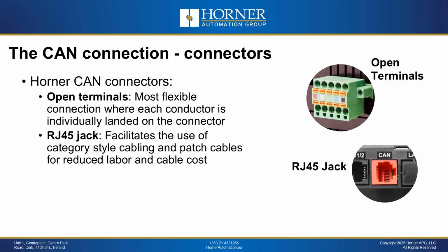Now let's start talking about how you can make that connection with CAN on Horner controllers. We're going to start with the connectors. Horner controllers have two different style connectors that they use for interfacing with CAN, depending on the controller. Let's start with open terminals. Open terminals is the most flexible way of connecting CAN in that you get a terminal strip included right on this CAN port on the Horner OCS or on the I/O block.